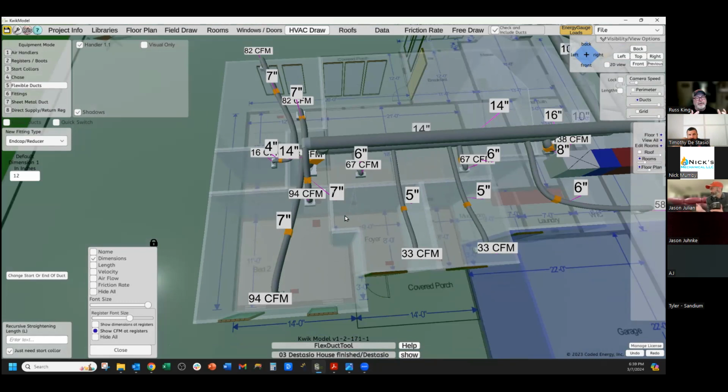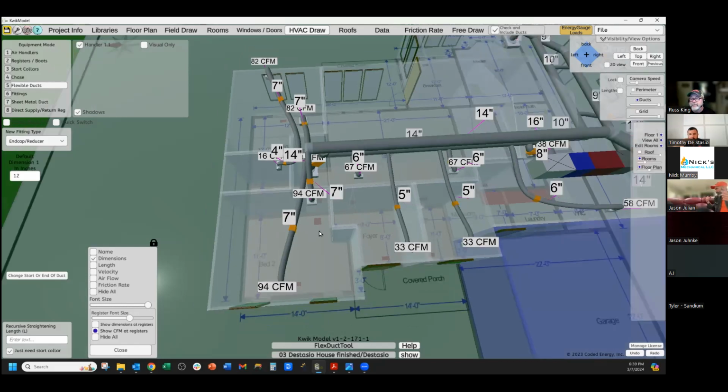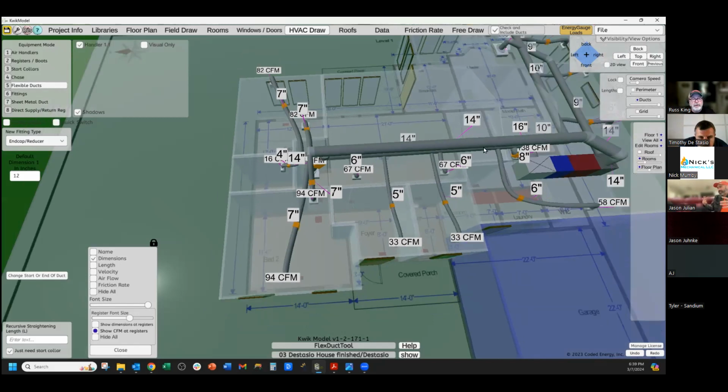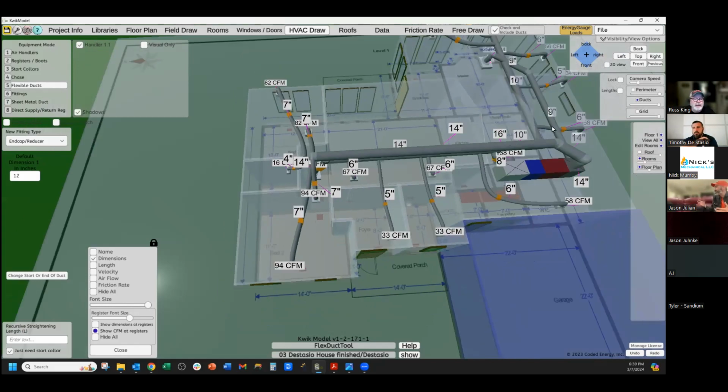But I think it's useful to know that this room only needs a 7-inch, but you're going to install an 8. And so that might mean that you may have to damper that room down. It may get more air than it needs, because air is going to take the path of least resistance. But it's always good to know, because you may get in a situation where an 8-inch won't fit, and you'll say, okay, well, how bad is it going to be if I put in a 6? Well, if you know a 7 is only needed, it's not as bad as downsizing from an 8 to a 6 as from a 7 to a 6. And maybe you can shift some load around and things like that too. So I think it's useful to know the exact size duct that it actually needs.